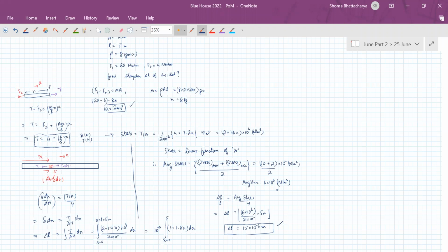Okay, sir. So a heavy rod will have variable stress in two situations: if it's accelerated or if it is in a vertical position, so its weight is contributing to tension. You understanding now? Yes, sir. So in these two situations it will have variable tension. Sir, if the rod is massless, then it will have uniform tension. Sorry, uniform stress. Uniform stress, uniform tension. Yeah. Okay, sir.